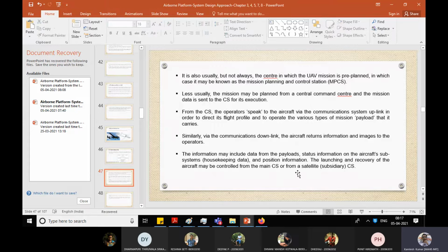You should not cross your range as per the radio communication link. If it is 230 kilometers, you should fly within a 230 kilometer radius. It should not cross; if crossing, you will miss the link. So you should have an autonomous facility which has return back options when there is no radio link. Normally these options will be there. If the radio link is not there, the aircraft should return back.